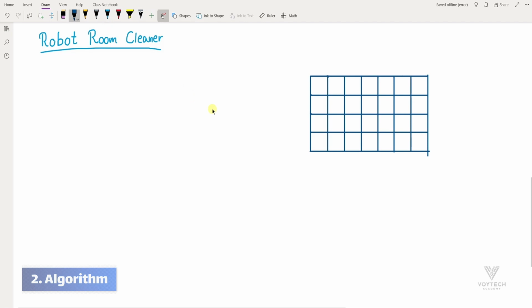So in order to explain backtracking, assume that these are the blocked cells in our grid. And also our robot's initial position is here and its direction is right. So when I move to the new cell, which is here, you can see that our robot is trapped here among 3 blocked cells and 1 visited cell. So we need something to go back to the previous cell and choose an alternative path instead of this path. So this is called backtracking.